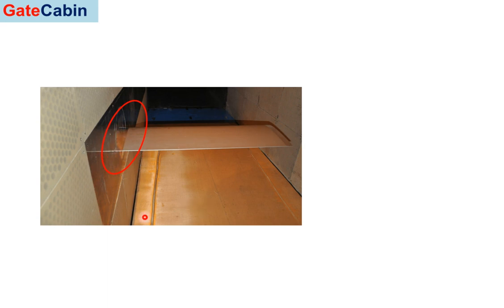So under laboratory conditions, whenever the studies are performed, the edges or tips of the wing are connected to the wall, so that the flow is not able to move in the third direction. It is able to move in the forward direction, and because of the presence of the aerofoil shape, this wing shape, it is able to move in the upward direction. So the flow is able to move in forward and upward directions. That's why it is also called a two-dimensional wing.